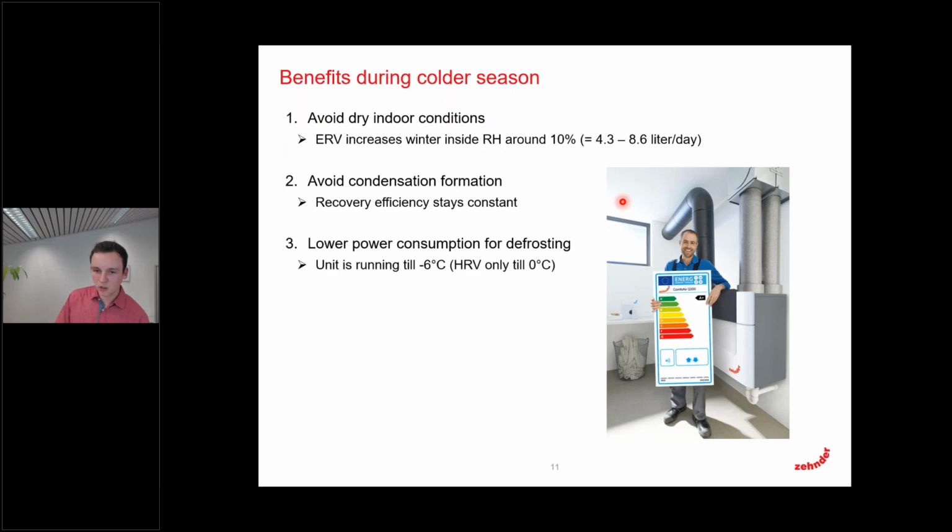So if you imagine that amount of water, I think it's quite a lot. You also avoid condensation formation because you recover the humidity. There is nothing to condense when you are using an ERV, so you do not need a condensate drain.